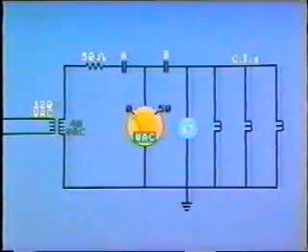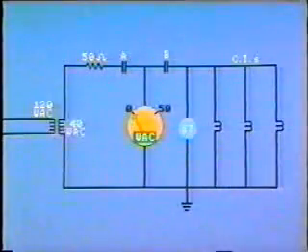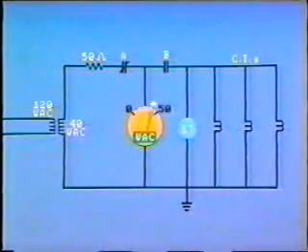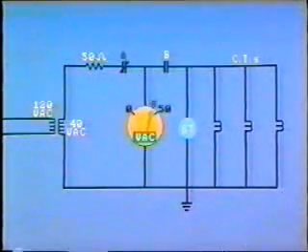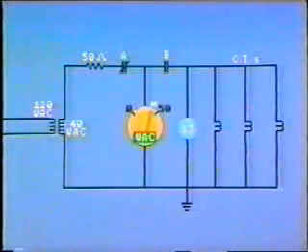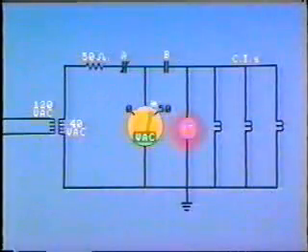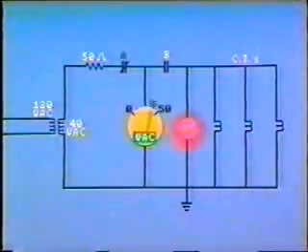Because of the importance of the bus in system operations, some installations include a supervisory circuit, which allows the operator to check the integrity of the bus differential protection circuit. This test circuit applies a low voltage to the relay circuit. When on standby, contact A is closed and 40 volts test voltage is available. Note that this is not sufficient to operate the high impedance relay.